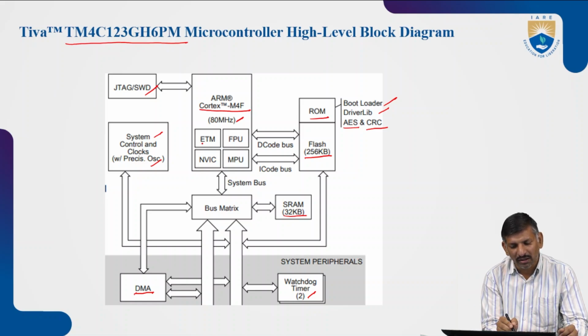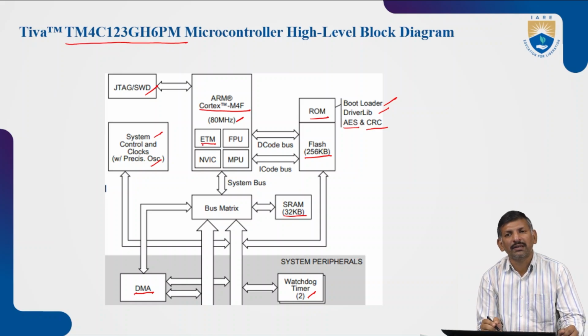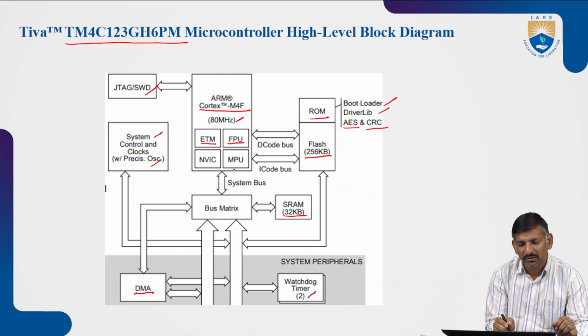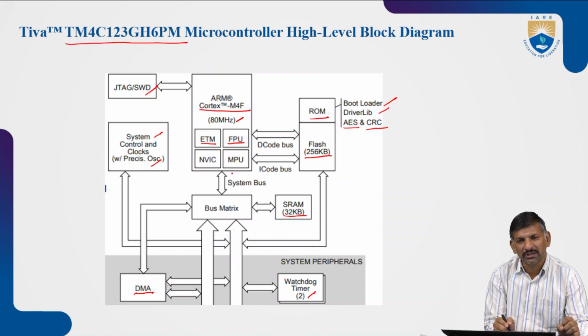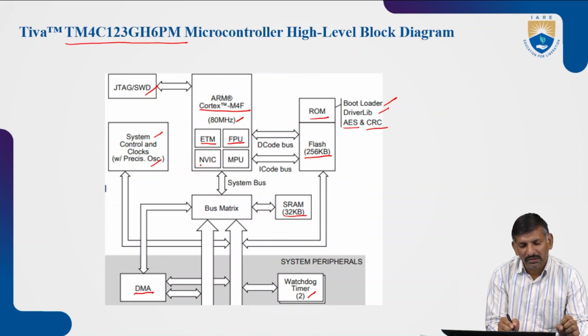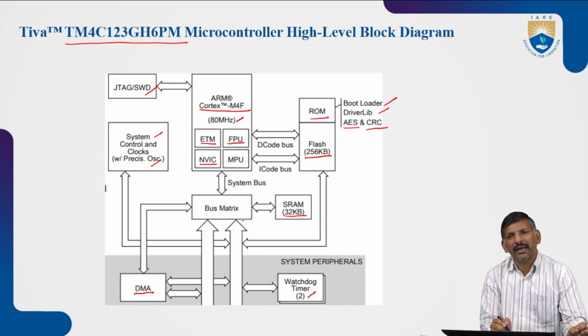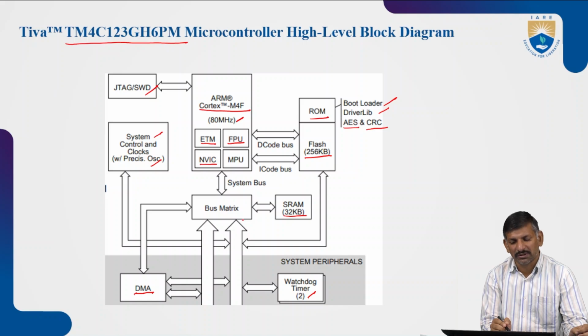It contains on-chip embedded trace macro cell. It contains on-chip floating point unit for doing the floating point operations, macro cell for debugging the instructions, and it contains nested vector interrupt controller for efficiently managing and scheduling the interrupts, thereby reducing the interrupt latency and improving the speed.